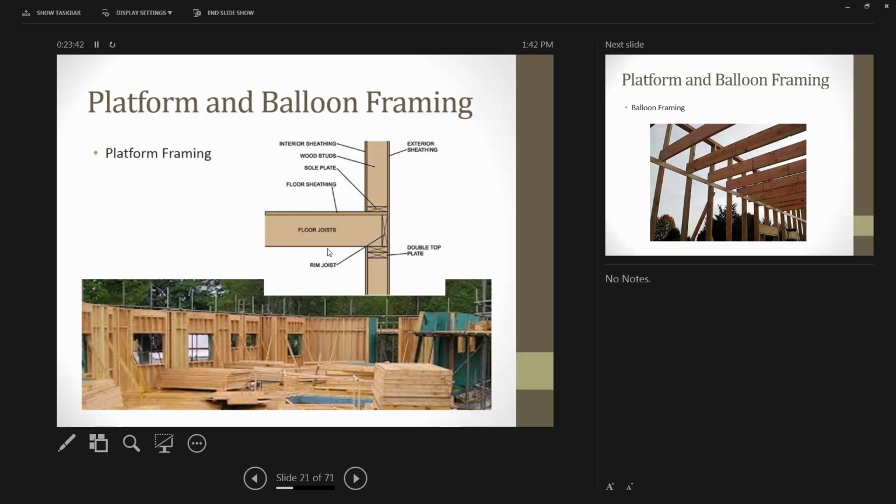And we'll do some thermal imagery work, and one of the things we'll do is hopefully be able to have everybody have their own time with thermal imagery and go out and do your own testing with it. But in a lot of older existing homes, when you're looking at thermal imagery, you see this red band between the floors, and it's this part that's usually not well air sealed, not well insulated.